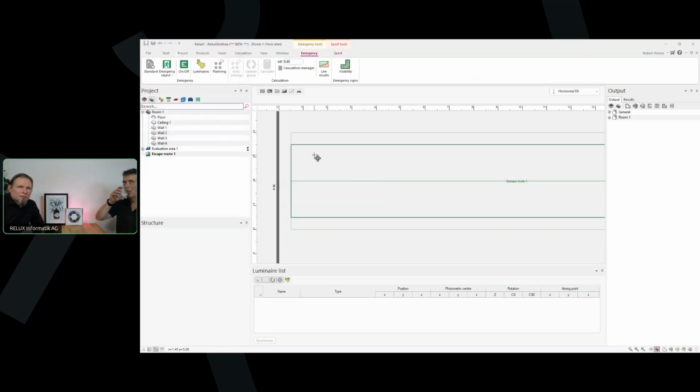But now you may have seen that we have a bit of a wider area for the calculation, for which 1 lux minimum is needed. Again, the midline is not really there. The midline is still there because we like to draw the escape route on the midline, but this is not an evaluation anymore. Now it's about this area.